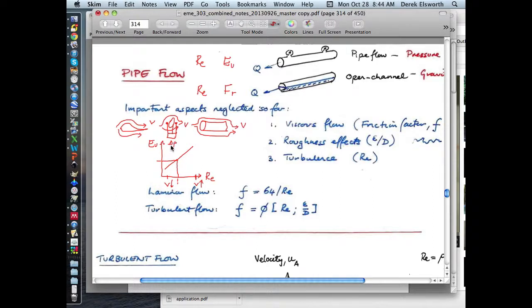That's the reason that it would bend and snap. If you look at a pipe, then that would be the same thing. If this was closed here, you'd have a pressure here, and you'd have a pressure on the downstream side as well. And it's by virtue of the fact that you're killing velocity here, but also you're getting some viscous forces acting along this boundary, which are acting as frictional behavior.